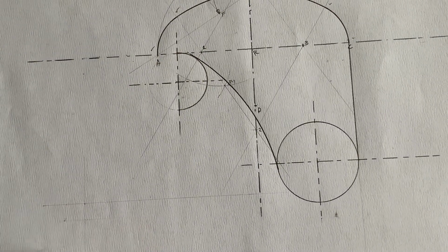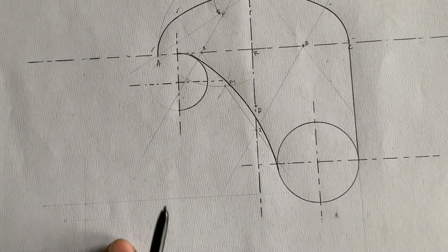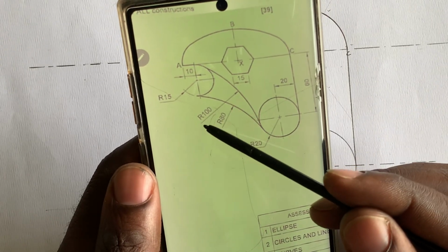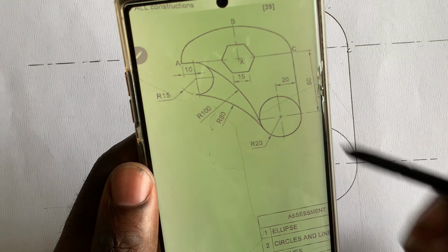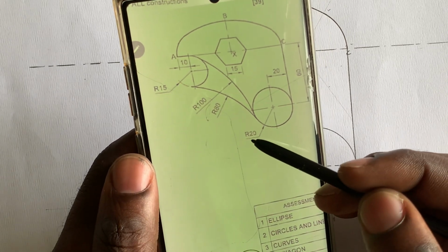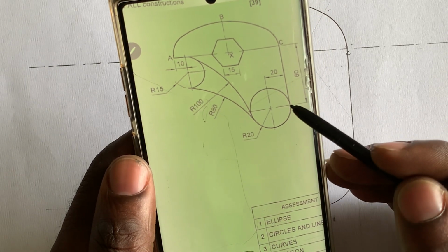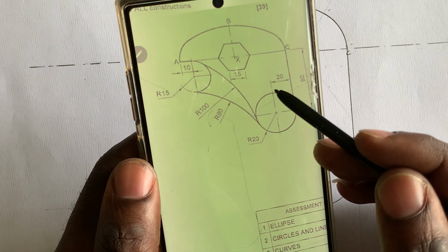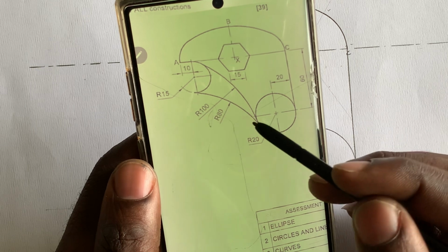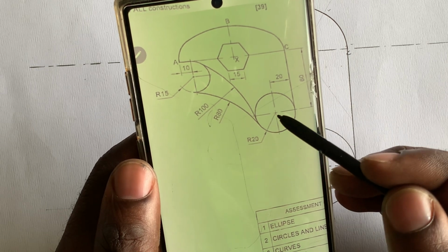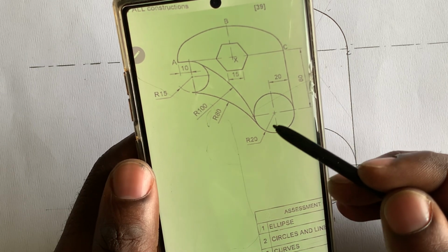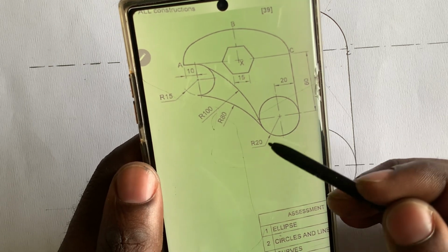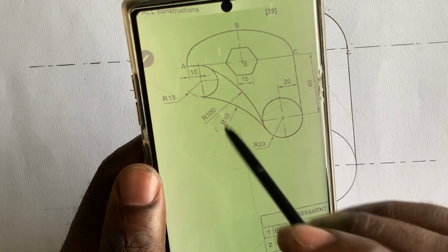So we trace it, trial and error method. You trace it like this because we were not given the radius reference point. If I'm saying the reference point, I'm actually saying, do you see this is radius 20? So we are told from here till here is 20. You understand? It's 20. So you construct a vertical center line and a horizontal center line. So you've gotten your reference of that R20. That okay, throw this radius 20, putting your drawing compass there. So again, this one